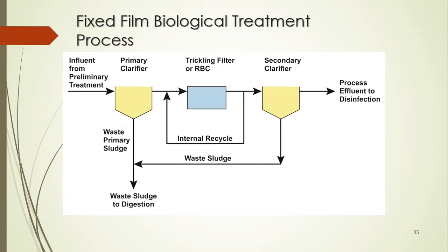You will pass the wastewater through the stationary medium so that during the travel of the wastewater through the filter medium, the water gets treated by removing most of the BOD, because the microorganisms attached to the medium will consume these organic substances as their food.